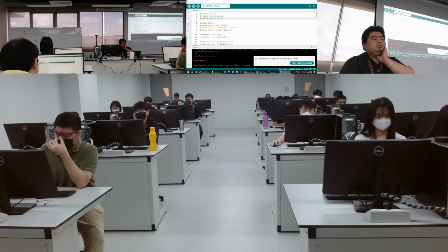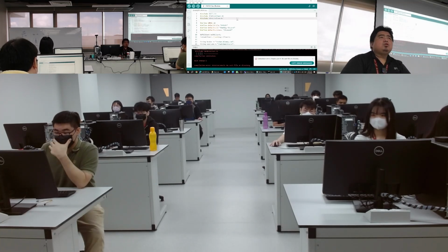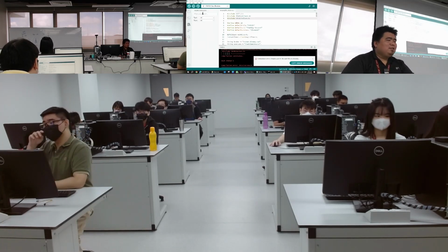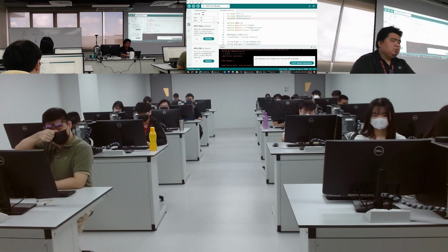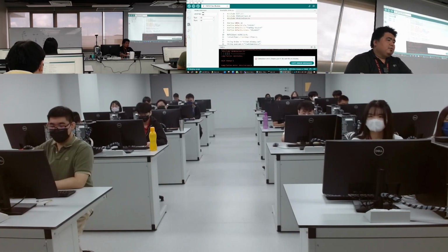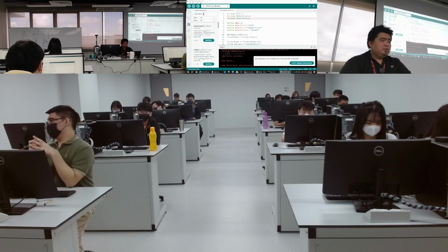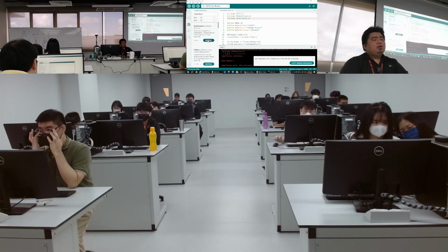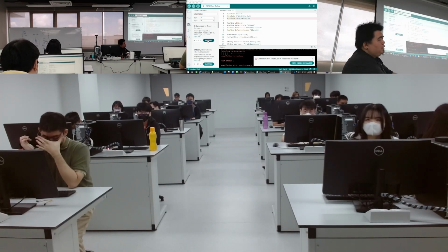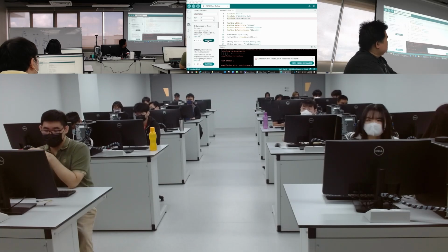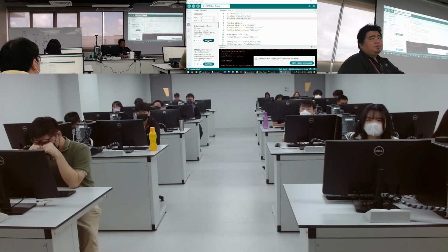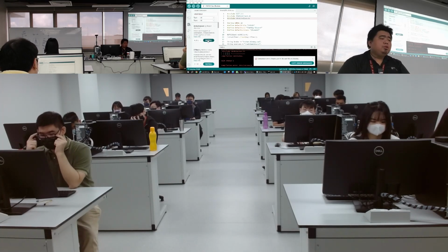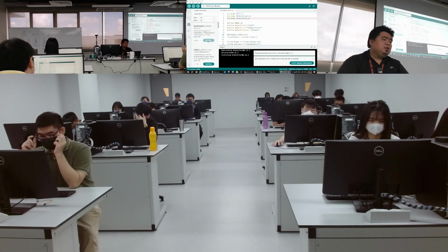Okay, there's an error again: the library is not enough. So we try to find the library, Arduino JSON. Arduino JSON by Benoit Blanchon, version 6.21.2. You can just install it.